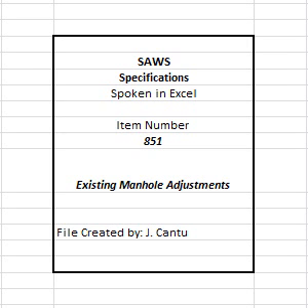11. Note of clarification, a minimum of 2 and a maximum of 6 throat rings may be used at each adjusted manhole. 12. Throat rings are limited to a minimum of 2 and a maximum of 4 rings for new manhole construction. 13. Throat rings shall not exceed 2 inches in thickness. 14. The sets of rings and covers shall be marked in such a way that they can be matched for assembly in the field. 15. All covers shall have the words San Antonio Water System Sanitary Sewer cast thereon, and shall be in accordance with specification item number 852, sanitary sewer manholes for further details.